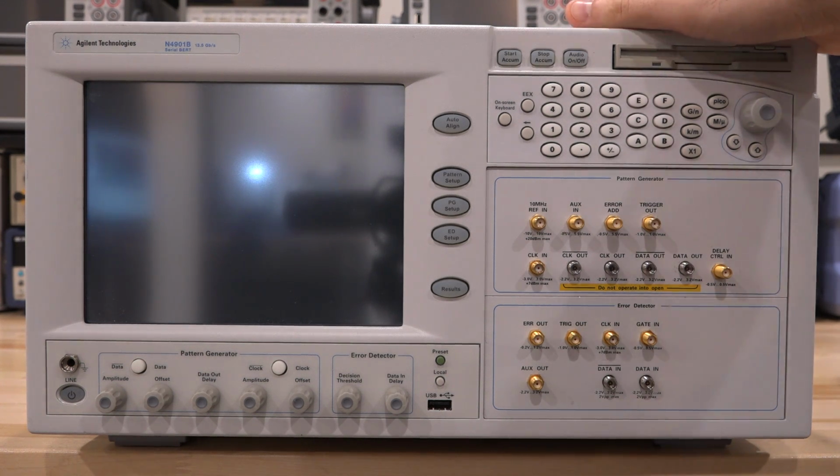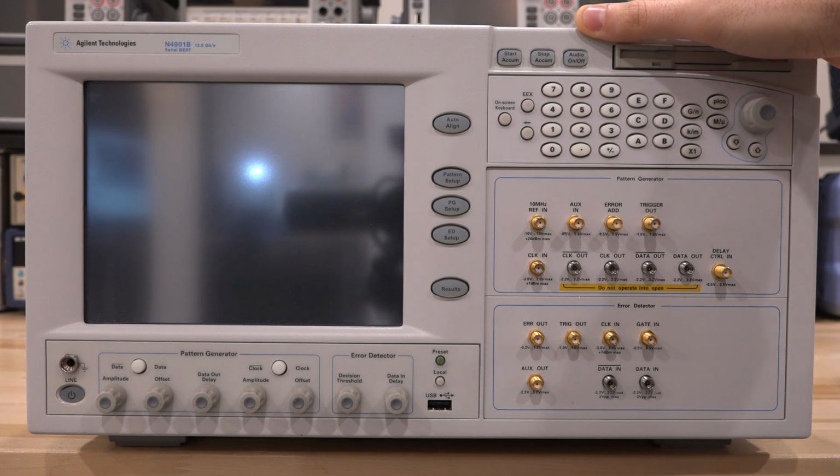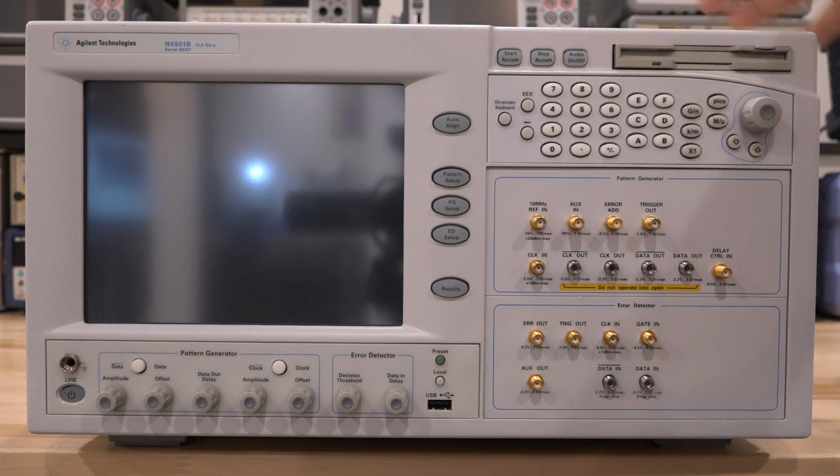Now this one has absolutely no sign of life, but its capabilities are incredible. It can do advanced modulation of the jitter. It can do error detection, of course. It can inject a particular pattern of error. It can do full eye diagram, bathtub curve traces, sensitivity measurements, you name it. It can do whatever you want. Really advanced. It's actually huge. This is a big, big instrument.